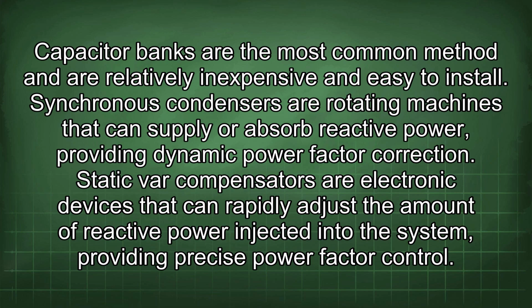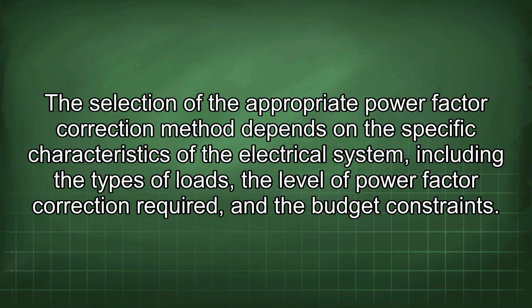Static VAR compensators are electronic devices that can rapidly adjust the amount of reactive power injected into the system, providing precise power factor control. The selection of the appropriate power factor correction method depends on the specific characteristics of the electrical system, including the types of loads, the level of power factor correction required, and the budget constraints.